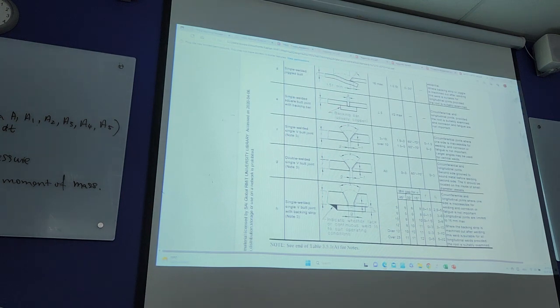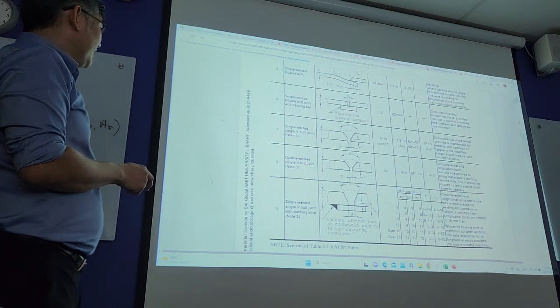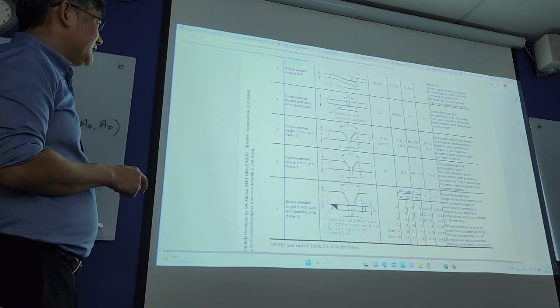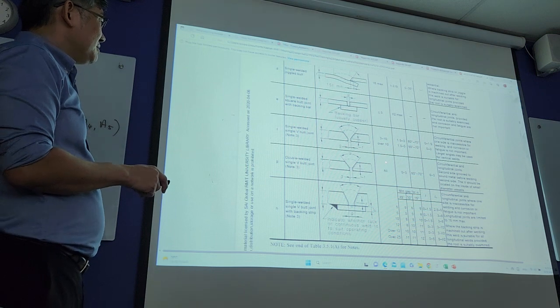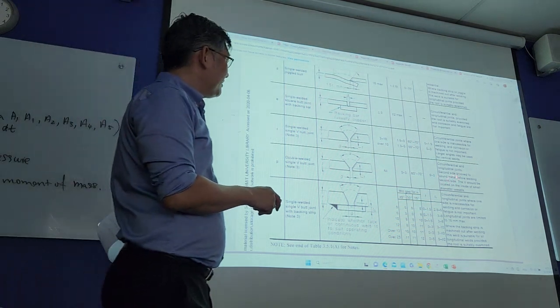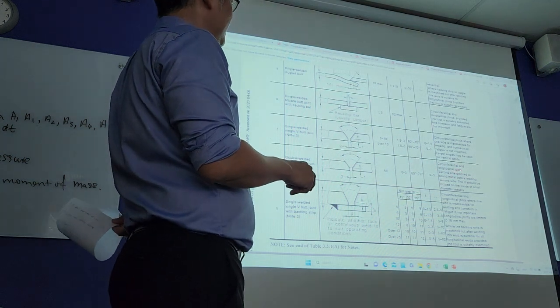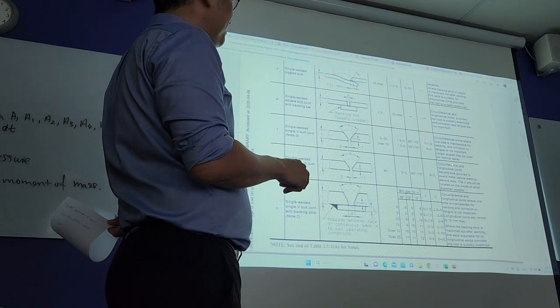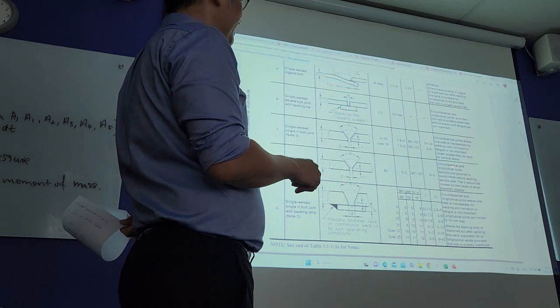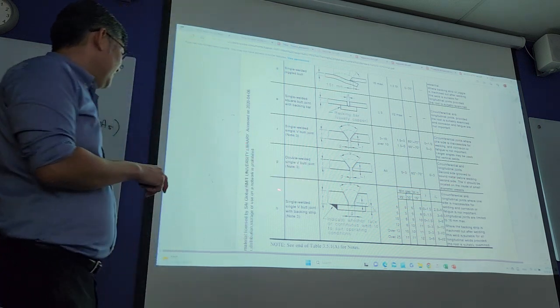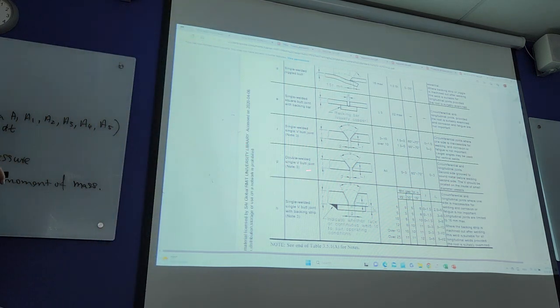So over here, I believe it's very safe. If let's say you recommend or suggest double welded single V butt joint, you can see the thickness applicable to all. Circumferential and longitudinal joint. You can see, applicable to what we discussed just now. Type B and type A, type of joint. If you look at this, of course, it seems applicable to our project.